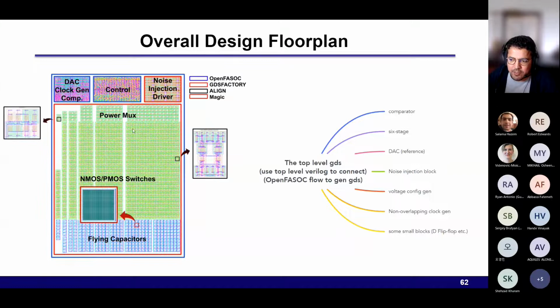In this case, we have done all the tools, as I was mentioning in my presentation, there's interoperability between these tools. Some of them use DEF and LEF, some of them use SPICE, and some just load the GDS in, like KLayout, or maybe I'm missing some part, you might tell me. So we had to create scripts, like Python scripts, to do parsing, which isn't great. It's not clean and it doesn't scale well. I don't want to say it's all automated, but it's a really painful step to do.